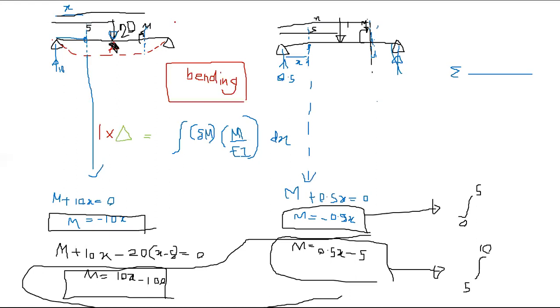So your rotational displacements correspond to a bending moment, so you need to apply a unit moment at the place where you need to find the rotation. So I'll apply a unit moment here. I need to find the rotation here, so I'll apply a unit moment.